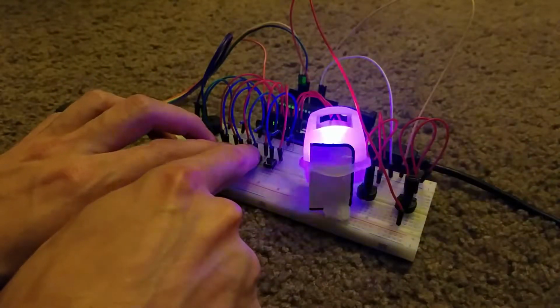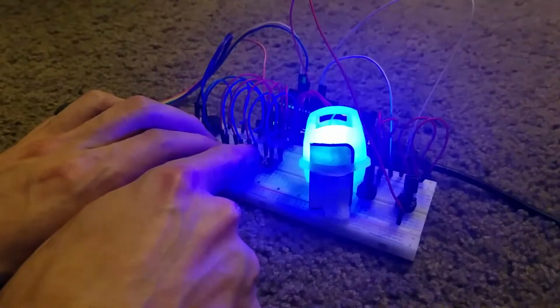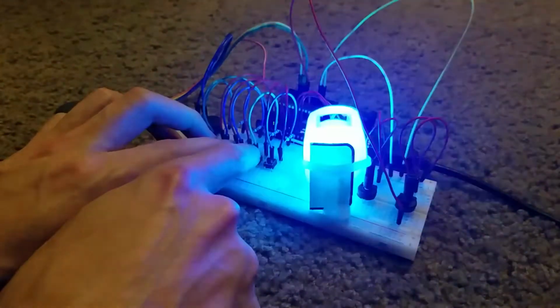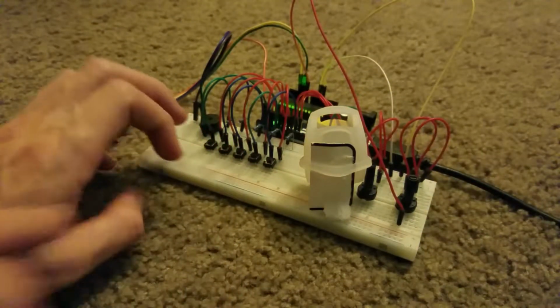I connected a 10K potentiometer to an analog pin as well as a joystick to 2 other analog pins, then both of them to 5 volts and ground. I directly linked the potentiometer's input value to note timer. It's a range between 0 and 1024, and this would be in milliseconds.